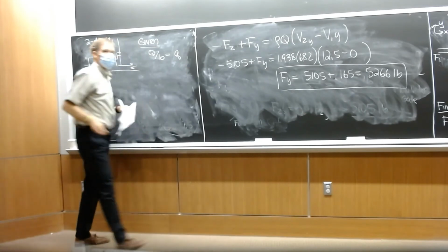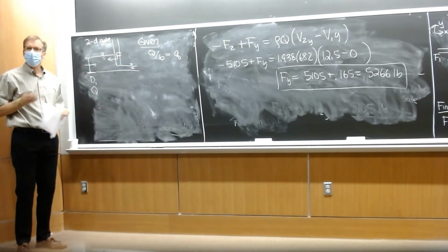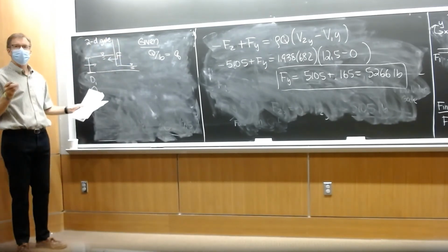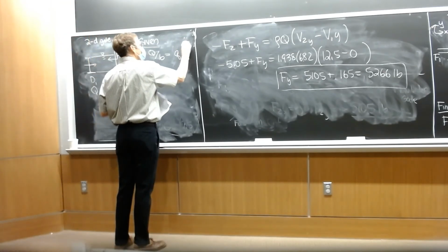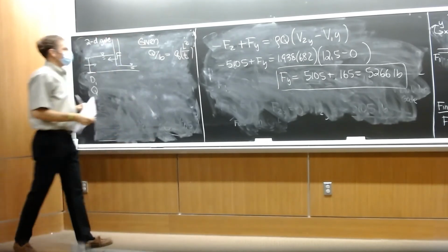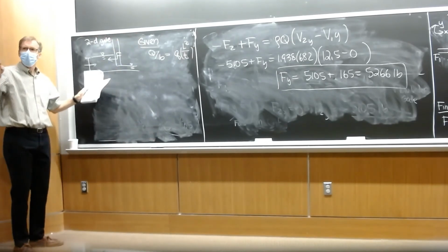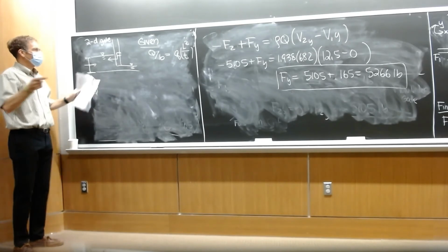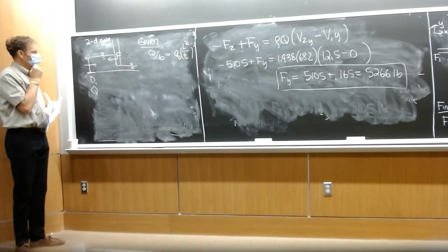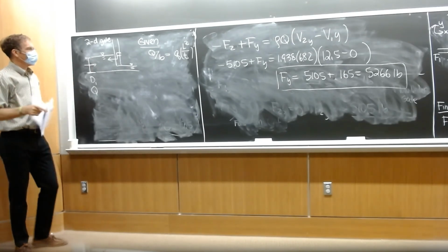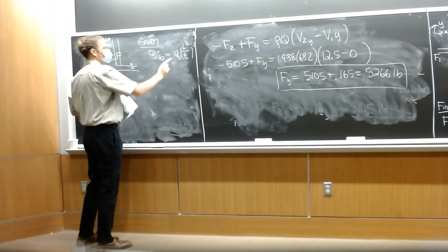We're going to specify the flow per unit width, which is given as little q. So if we had a particular width of the gate, we would take the flow and divide by that width. If you think of it as a very long gate, you might just specify the flow per unit length, little q.